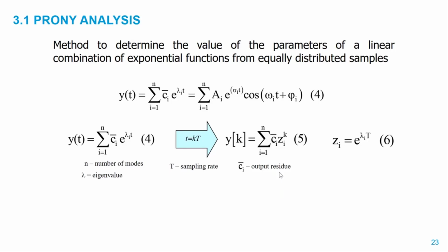Now let's go to the Prony analysis, which is, as we discussed before, applicable when we have a signal that is sufficiently excited. The dynamics are highly excited by a large disturbance, like a short circuit. Recalling the model that is used in this case, that is a summation of weighted exponential functions, or its alternative representation in terms of exponential functions and also a trigonometric cosine function.